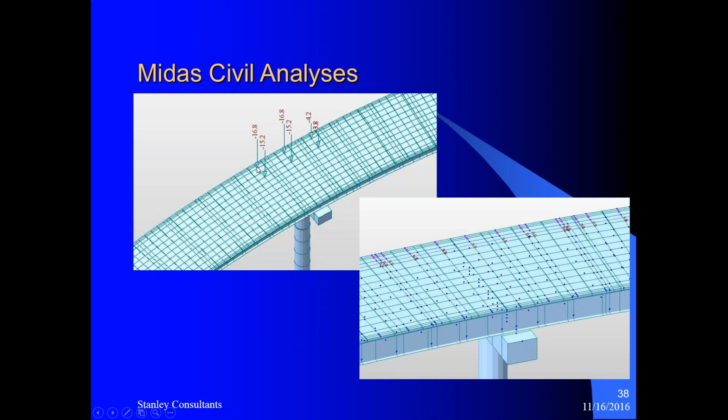As you see, due to curvature, the outside wheels have more reaction than inside ones, so you can accurately put the wheel reactions on the deck. And also the centrifugal forces you can apply to the deck as element or node static forces. You need to do a little calculation, but then you can apply these.